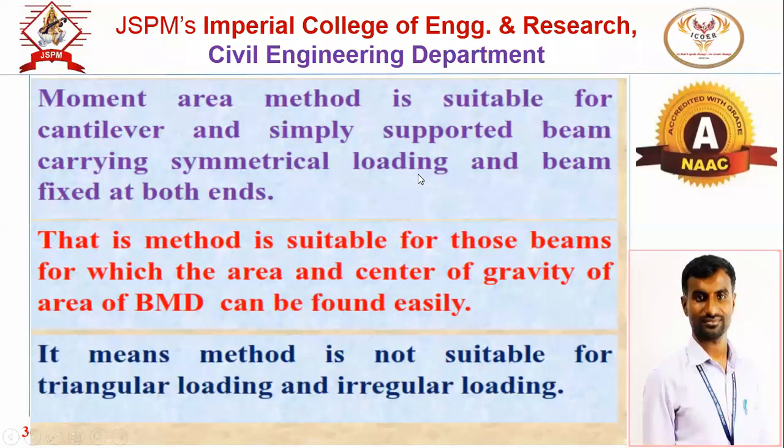Now this moment area method is suitable for cantilever beam, simply supported beam having symmetrical loading conditions, as well as fixed beam, means statically indeterminate beams also. So what is the advantage of this moment area method? We can apply this method for statically determinate structure as well as statically indeterminate structure. For both the structures, you can apply this method.